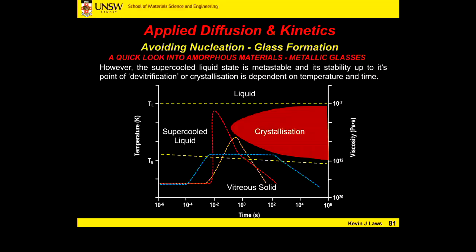But there's also a contribution from the liquid phase. At this composition, or very close to it, the liquid phase is also very, very stable. Is that why the driving force is very low, because the liquid is very stable? Yes, and at these compositions, the liquid's much less stable, the crystal's more stable. So it's always a competition between the two. Many people forget about L, the liquid. They just focus on the solid and the crystals, but it's really got to do with the competition between liquid and solid.